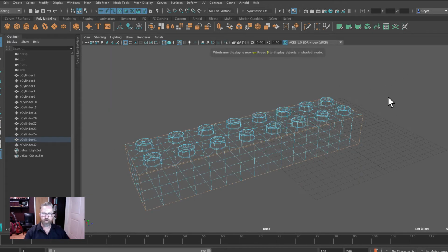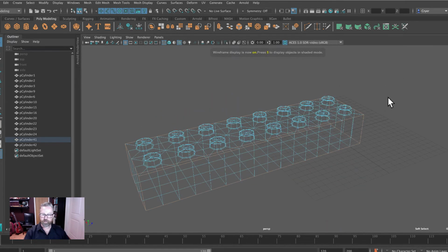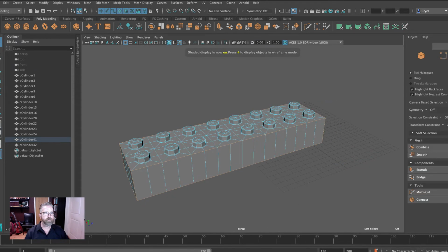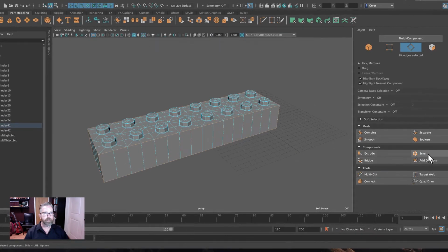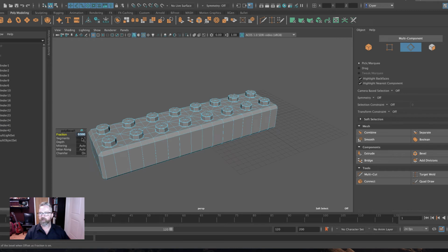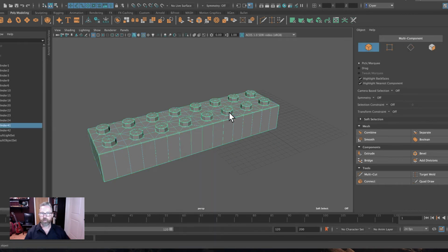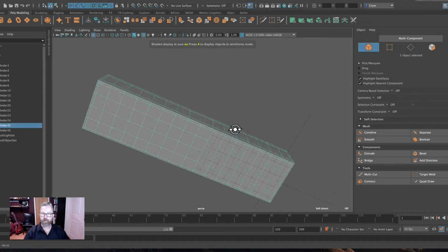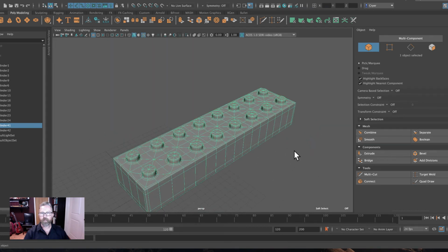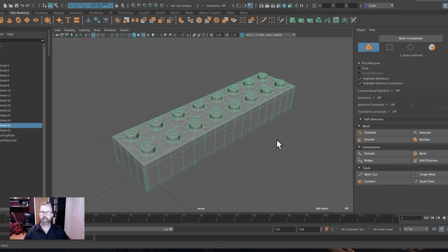So we've got all of those exterior edges, and we're in business, and we're ready to now hit bevel, our fraction 0.1, our segments 2, and object, 5 key, 3 key, dolly around, and here we have a 2x8 bevel, a 2x2 brick bevel ready for export.